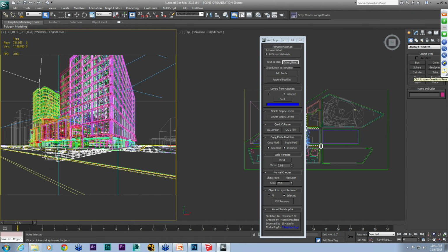I guess I would ask, what does he mean by weird-looking polygons? Is it something where the polygon is subdivided, like it's got triangulation to it, or double geometry? Like if you're in shaded mode and panning around, you're seeing the black, like half black, half material in your shaded view. It might be that there's double geometry, which again, having your things layered out by material, you can start to see where those things are doubling up. No reply yet, so we'll move on to the next question and then we'll come back once he replies.